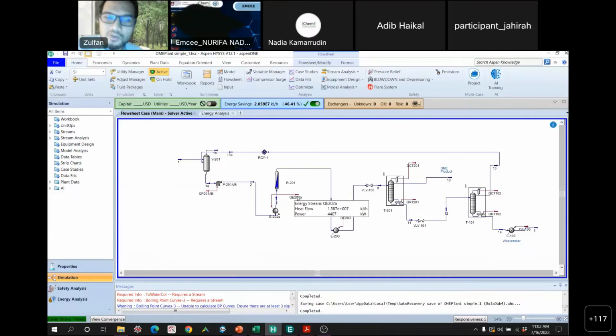So how do you know this? You make the mass balance. How do you make the mass balance? Well, you can do process simulations, getting data from the field, or getting data from the field and then making your own Excel sheet or whatnot. So for sure, you have to make the mass and energy balance simulation. And then we have the conversion, and roughly 80% of the methanol is converted. So that means 20% is going to come back. This is the 20% of unreacted methanol over here.